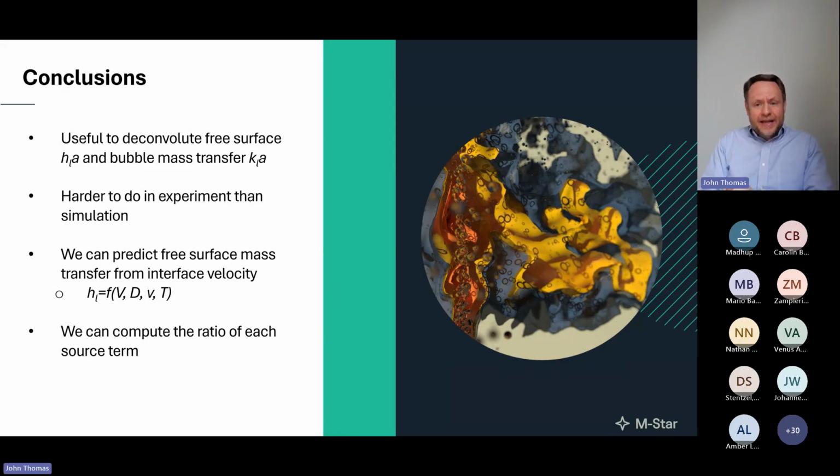If we're trying to characterize it, make sure your headspace is well stirred. I really hammered that point with those three plots converging with increasing gas flow rate. Go back and watch the tape if you want to see that a bit more. But to isolate the free surface transfer effects, you've got to make sure you have a reliable driving potential. To do that, you've got to make sure you're in an open lab, or have a very well stirred headspace if it's a bag. But again, I said HLA, and quantifying it is important because we oftentimes put value and benefit on the bubbles when they did nothing to deserve it. It was all the HLA carrying the water.